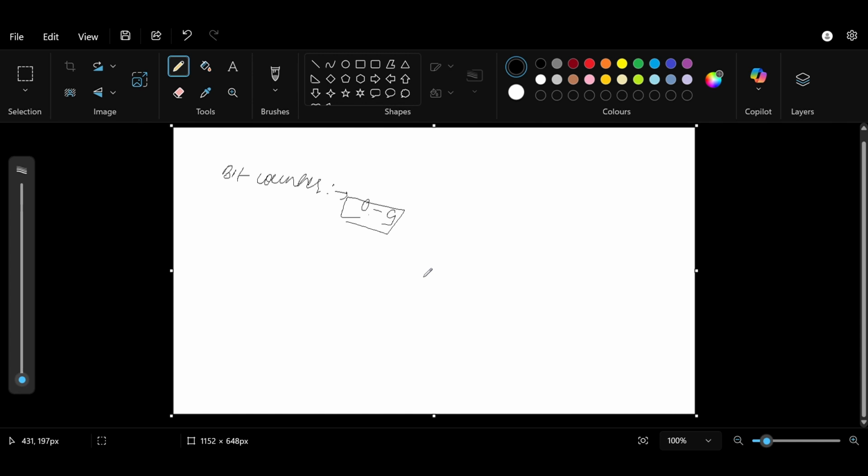After receiving the 10 bits, the valid signal is set high. The sampling of each data bit is done at the middle of the bit period, and after sampling, the bits are moved to the RX data.